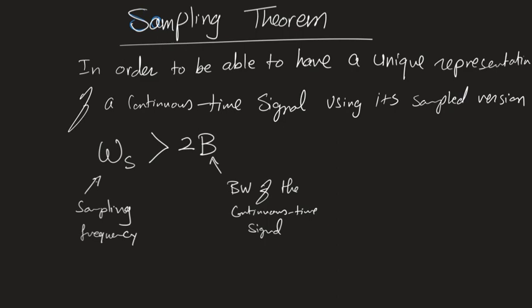But if you go below the minimum, if you go below what this theory says, you will never be able to recover the actual voice on the speaker. You will just get something that does not mean anything, some noise, but you will not get the original voice when you try to produce it at the speaker, because at that point it has to be continuous again. Anyways, so that's basically what the sampling theorem says.